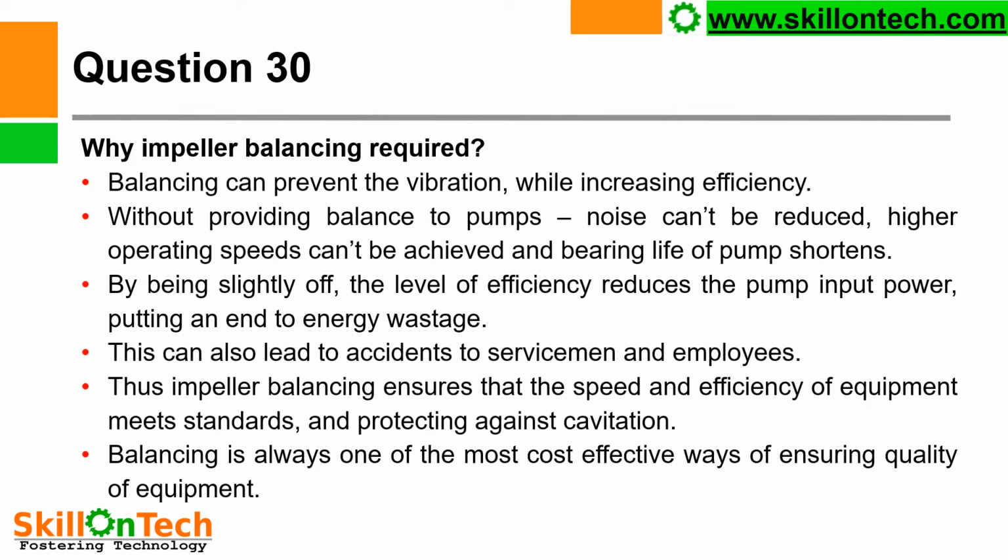Without providing balance to pumps, noise cannot be reduced. Higher operating speed cannot be achieved and bearing life of pump shortens. By being slightly off, the level of efficiency reduces the pump input power, putting an end to energy wastage. So your unbalanced impellers will also reduce your pump efficiency level and your pump input power will be increased. So there will be a wastage of energy.